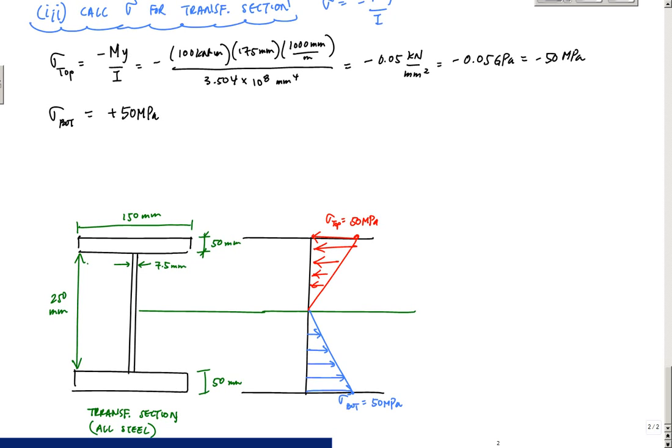And really, what you've observed before is that in order to go back to the composite section, this point right here, where my material transitions from steel to wood, is really important. So in terms of my transformed section, let me calculate these two stresses, and I can do that just by similar triangles. Here I have this distance, which was 175 millimeters, and this location right here at the transition, I'll just call sigma 1.